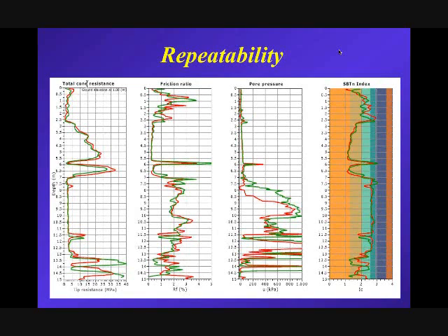But then you can see it became saturated again and started to respond quite rapidly. So what we do tend to find is that the pore pressure data tends to be used in a more qualitative sense for onshore CPT, partly because of the difficulty of ensuring whether or not that sensor maintains saturation. In the offshore industry, pore pressure is used a lot because they can essentially guarantee that the sensor remains saturated if you're in deep water.